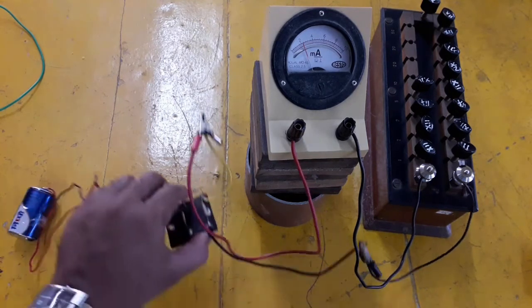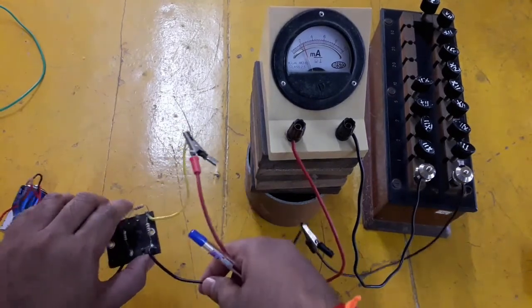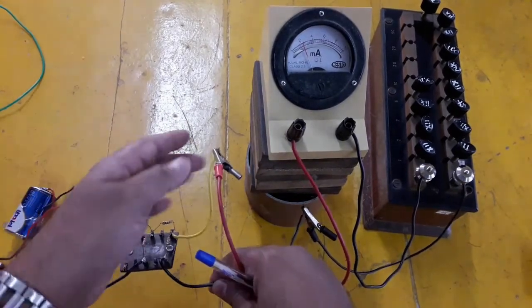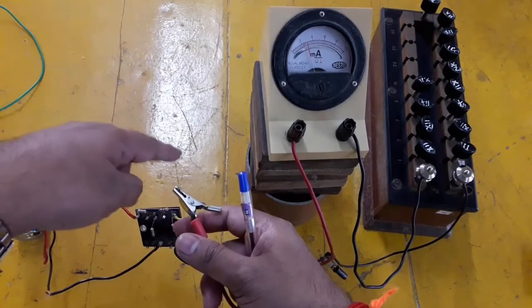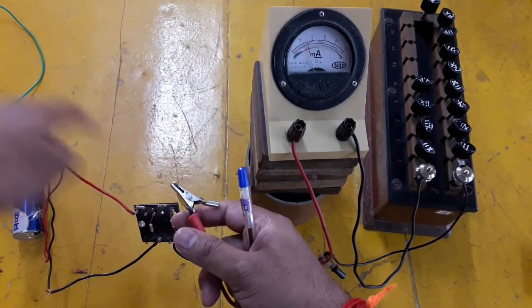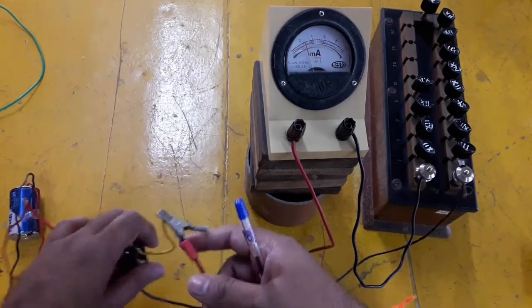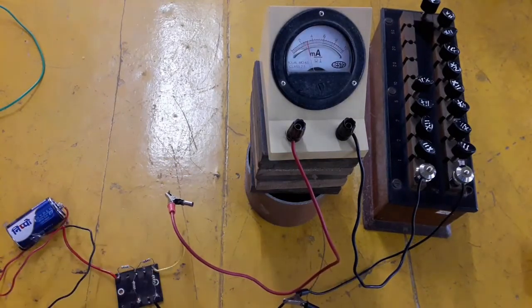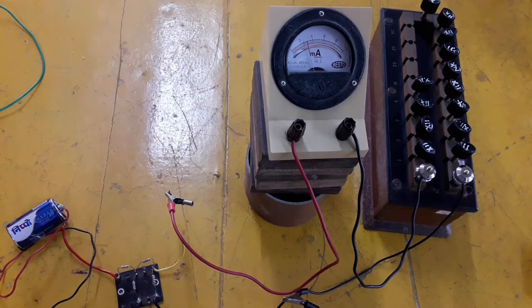This will get totally replaced. Okay, so this will go now from here. This entire part will go, and it will be replaced by one resistance box over here, which will be your RTH, and another one voltage source, and we'll take the readings all over again. Fine. So let's take a small break, then we start with part 2.